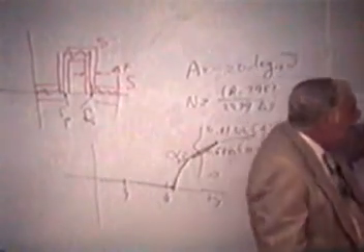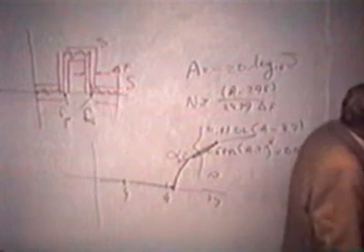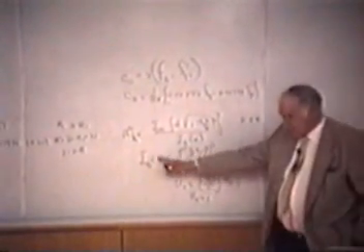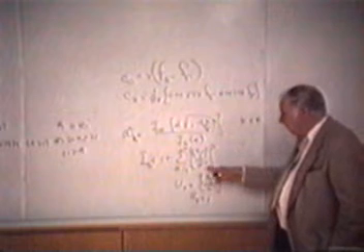You calculate the C_k, provided you've got a bandpass, bandstop, little small changes. Then you window with this peculiar function. I0 is the Bessel function of pure imaginary argument. And there's the k for the term, there's the n number of terms you took, and there's an I0 down below, and I0 is simply this power series, 1 plus the sum of (x over 2 to the n, over n factorial) all squared.